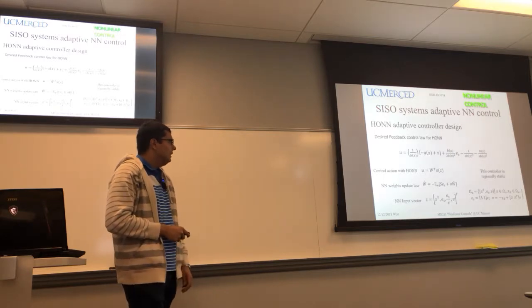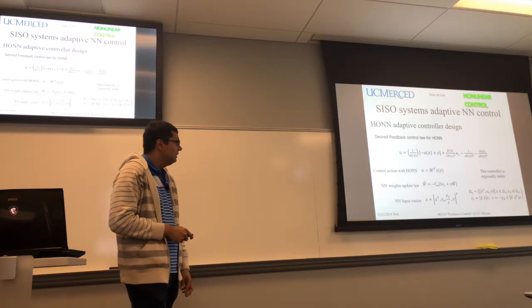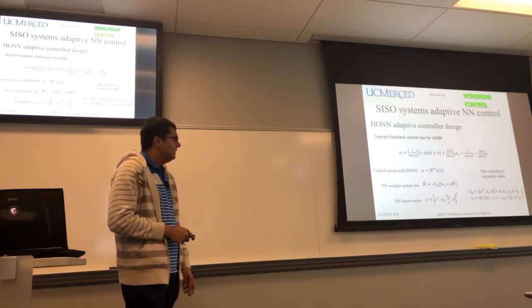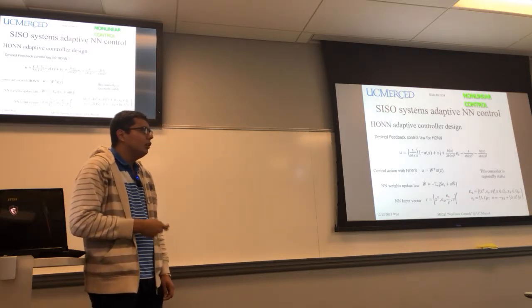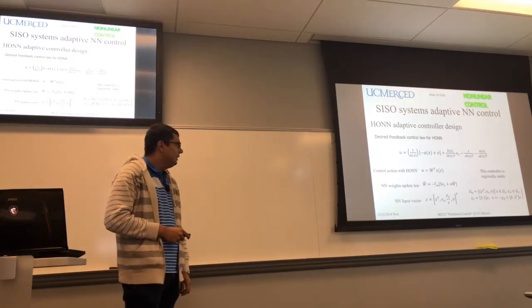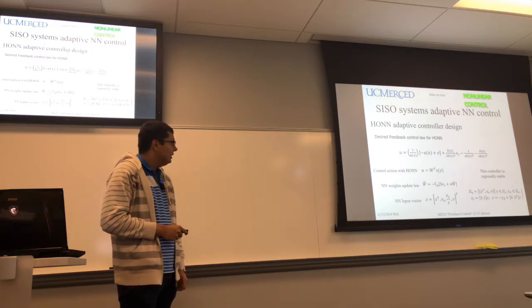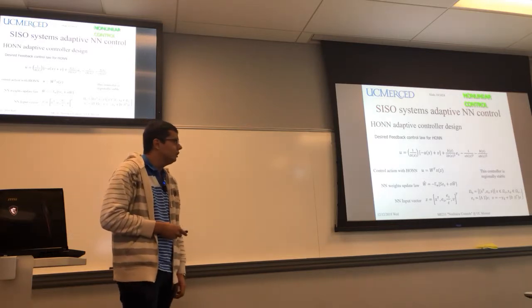So this is the update law selected for this specific control law, and this is the input vector. This x of t, this x transpose, are the states of the system. The sliding surface over epsilon. This epsilon is a tuning parameter to improve the robustness of the neural network and the controller. And here, this controller and this neural network is bounded by the input and bounded by the omega c subset.